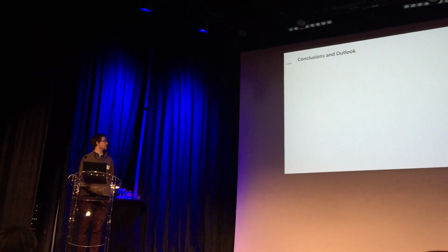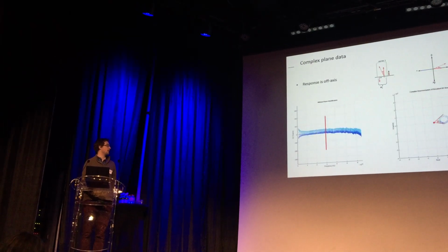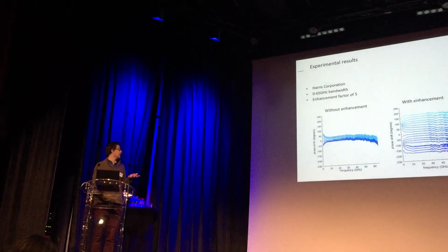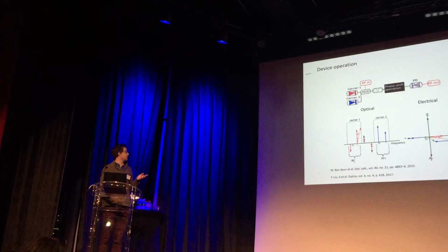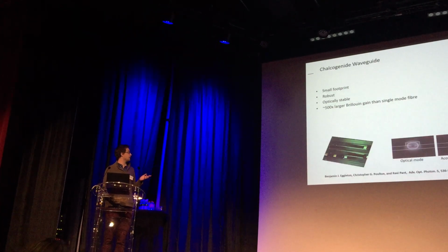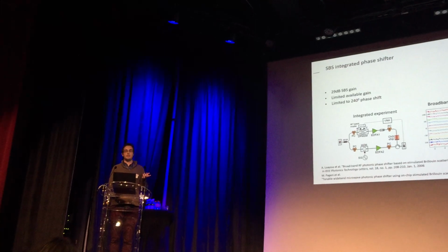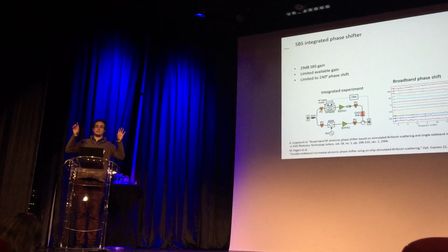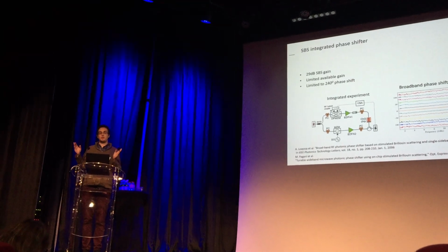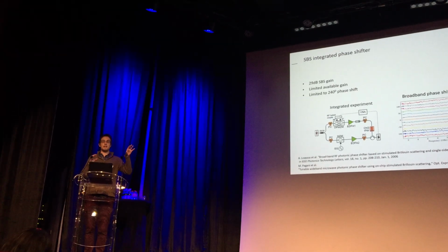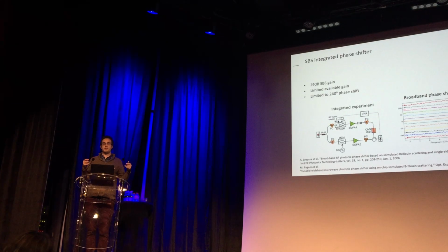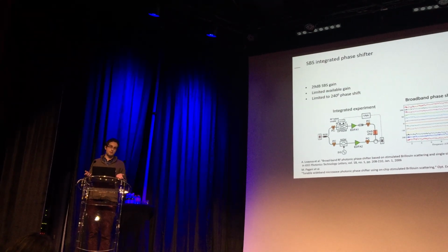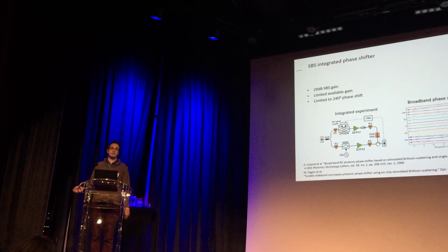Well, in many instances it's useful, but it comes from the Kramers-Kronig relation. But if we go back to this work here, hang on. So with SBS, there's a gain resonance, but on the opposite side, there's a loss resonance. So if you were to put in a second laser, you could use the gain and then the loss on top of one another to give a very flat amplitude response. So there are options if you wanted to do that.